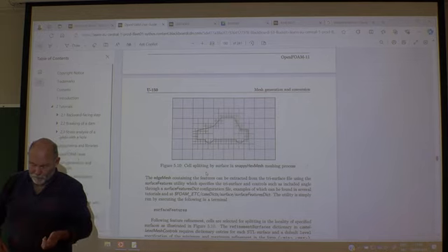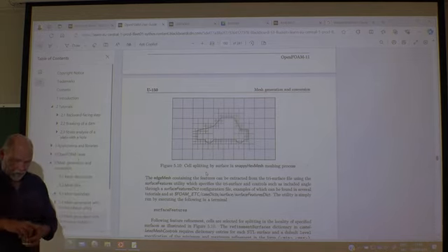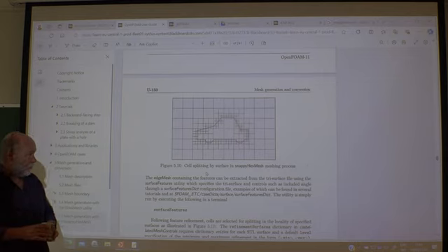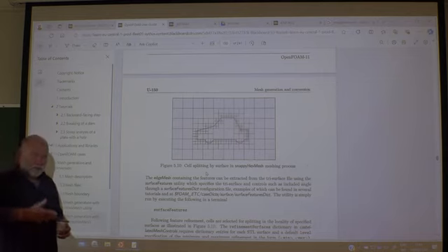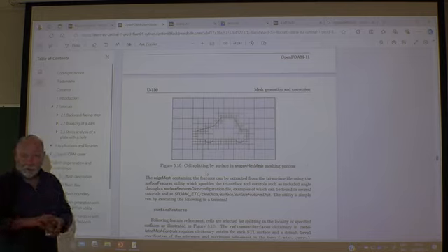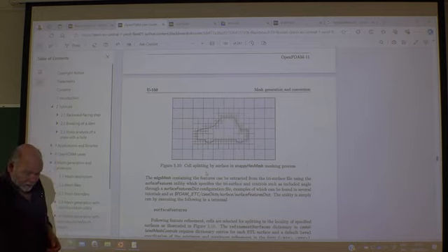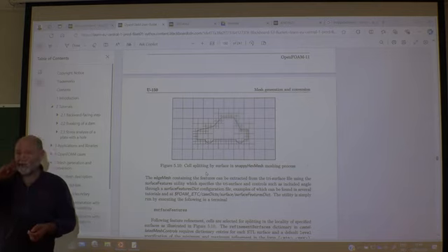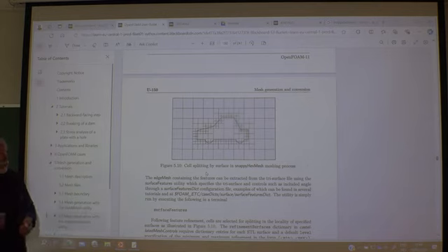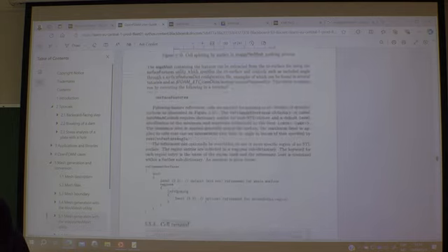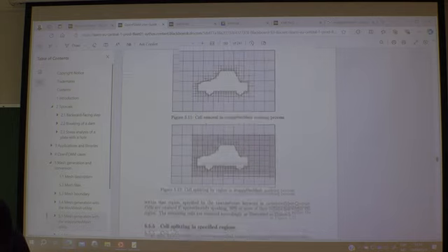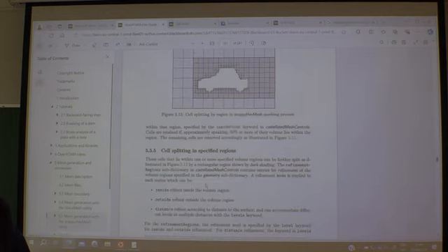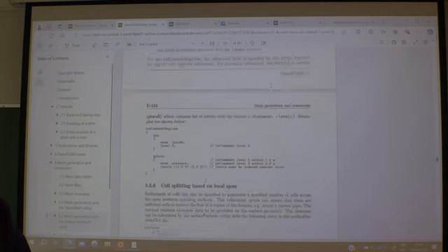You have the possibility to have a setup for snappyHexMesh, a recipe, and then it's done for you automatically. But it's complex, and setting it up yourself is not for amateurs. You have some 20 different parameters or something that you can play around with here. And the result may actually be fatal. You can end up with a very bad mesh unless you know what you're doing.